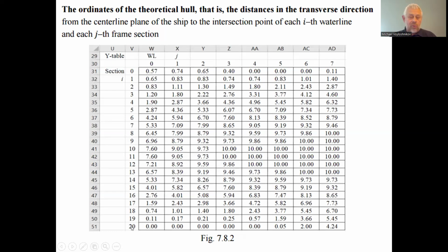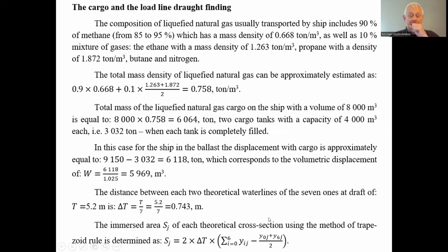Sometimes people can have more than 20, but for theoretical calculations such as the check of the strength of the ship hull, considering the redistribution of the Archimedes force along the ship length, the distribution of the submerged volume and the corresponding distribution of the buoyancy force, we can consider 20 accurate enough for approximate calculations at the technical degree of approximation. Okay.